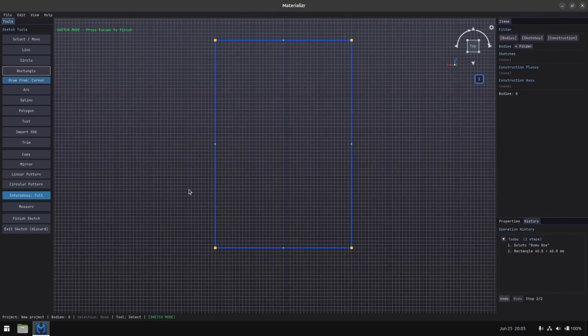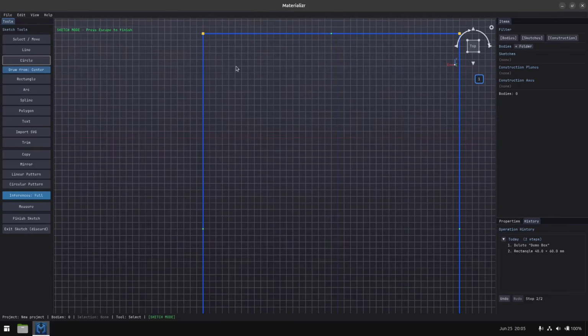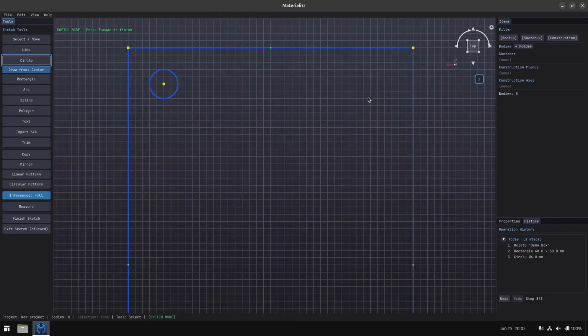For the project box, I'm not going to be using much of this, but we'll start with the rectangle and a few circles in the corners, because what's a project box if you can't fasten it closed? So we'll put one there, and here's the inferences at work already. We are going to symmetrically place the center of the next circle here, go to 4.